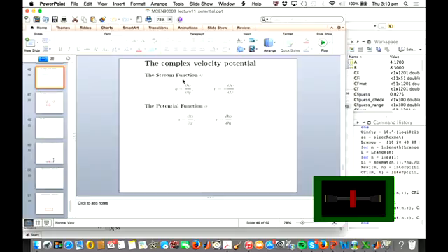I mean, what I would do is then plot the lift to drag ratio, which right now we don't know anything about. And then I think what you'll see is that there's a region at the top where you've got quite favourable lift to drag coefficients, and then when you exceed that stall, I would expect the lift to drag coefficient to come right down.